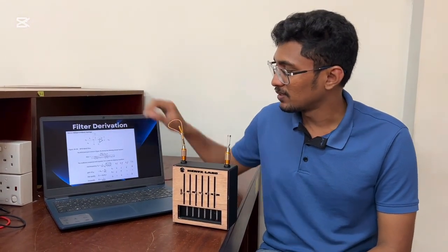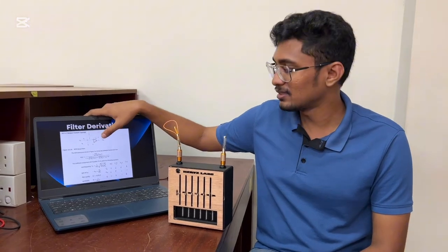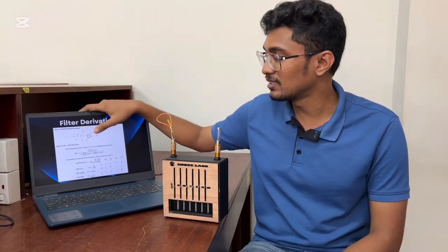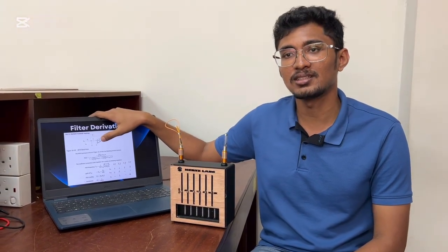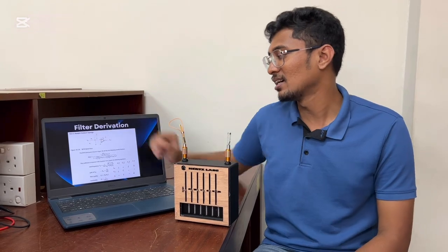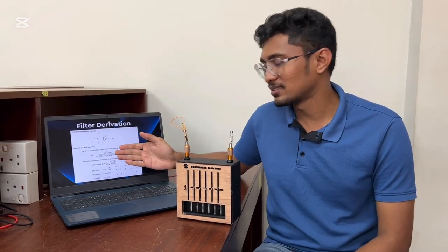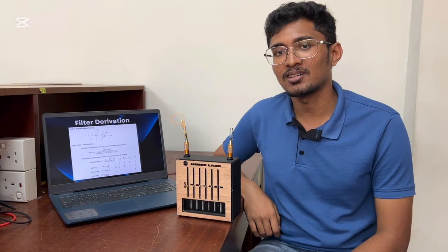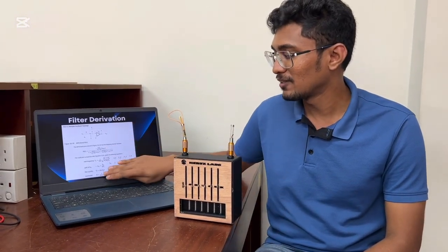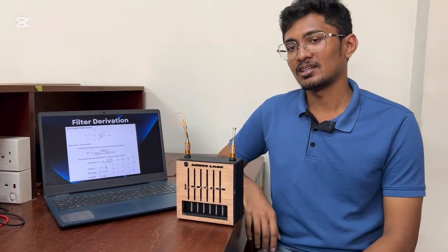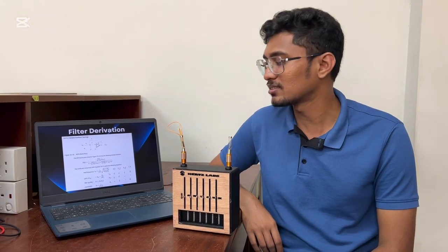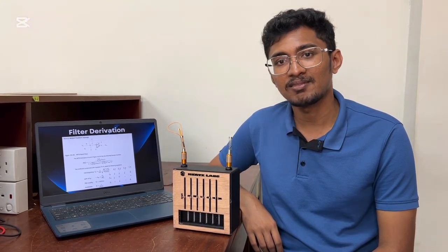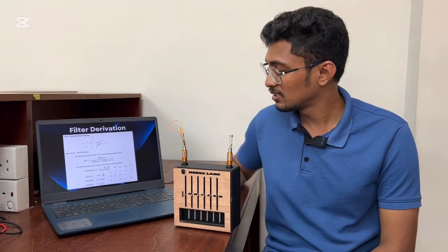This is the circuit of our single filter, which is a Sallen-Key filter, and two of these filters are cascaded to form a single band. We have used this transfer function to analyze our filters, and the results are shown here. That means we have precisely calculated the mid frequencies, the gains, and the bandwidths of these filters.